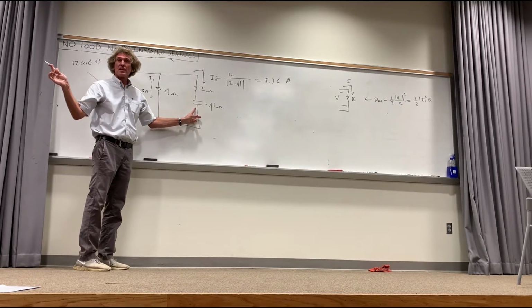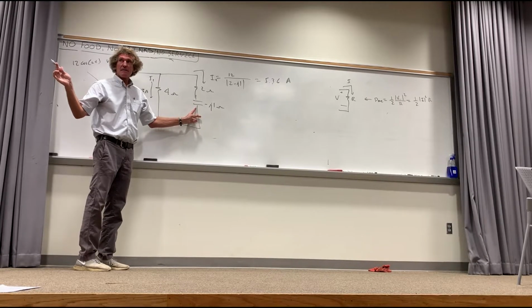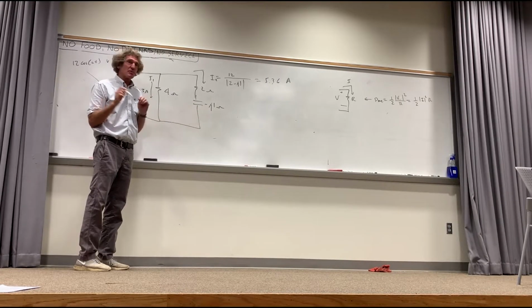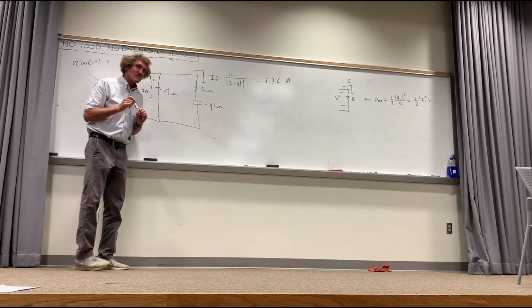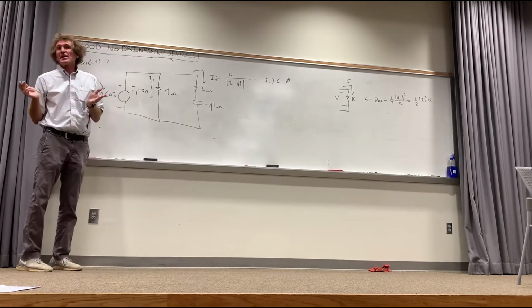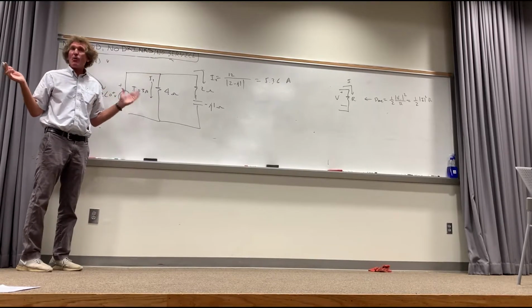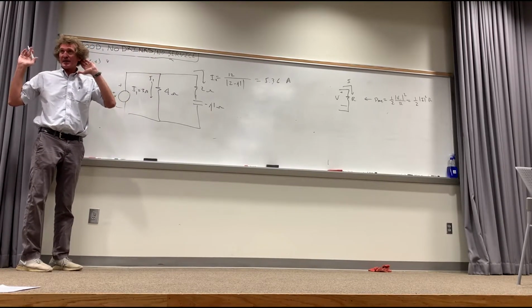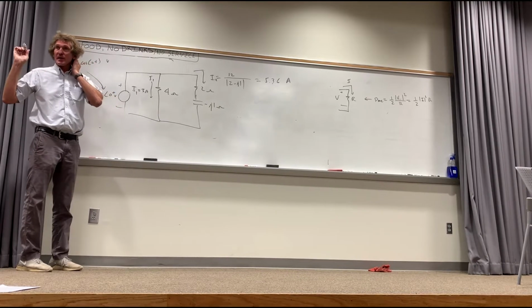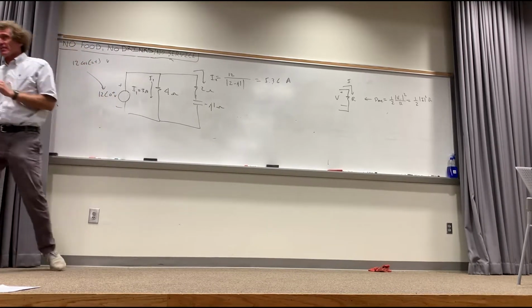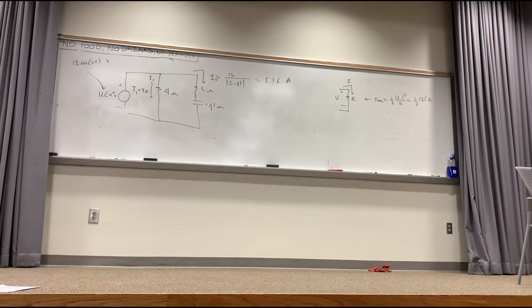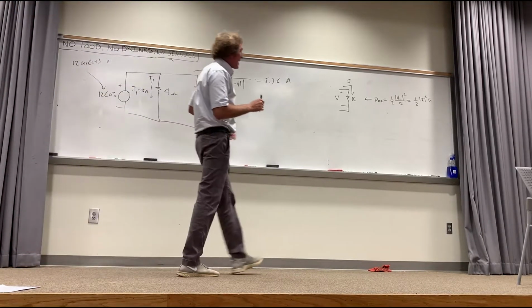Yes, miss. Could I just combine them, like have them in parallel since I can combine the two into series? I want to know what you want to put in parallel. Okay, for the impedance, like. We don't need the impedance. We got the current, don't we? Oh, okay, yeah. We got the current. That's all we're after is the current through these elements. Got it, class? The current tells the tale. Because only the resistance has average power that's dissipated. The inductor and the capacitor don't. We're only after average power, not instantaneous. So what happens here?